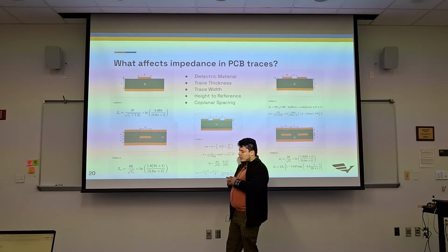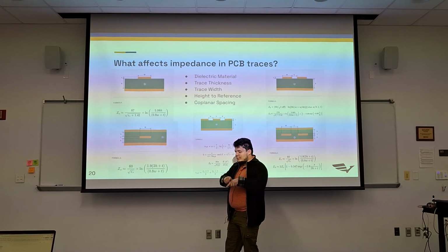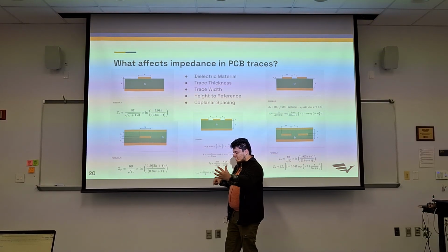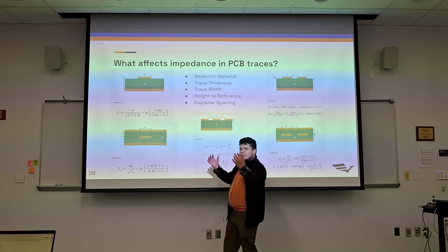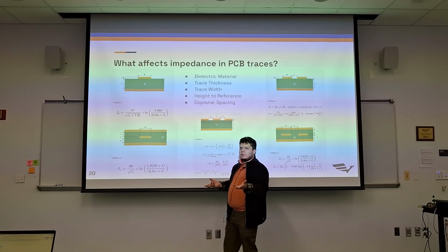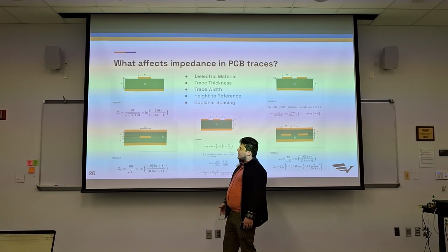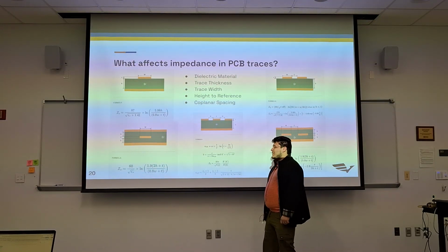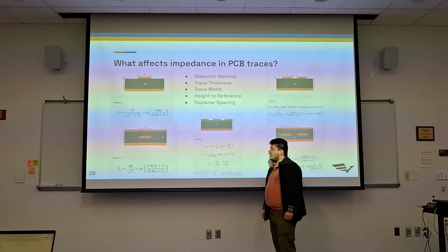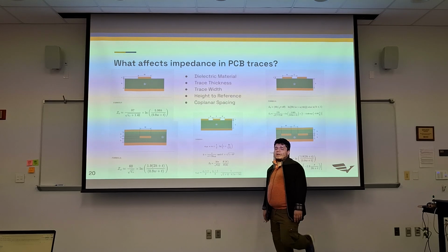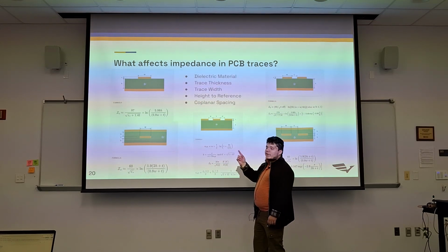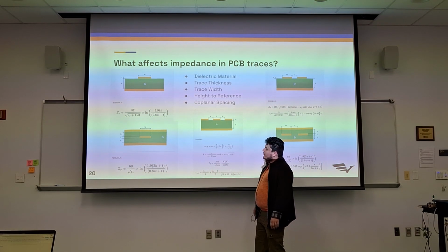This is good for when you need a very specific RF signal to travel from one board to another, and you need that shielding on top and the bottom because it's in a noisy environment and you don't have a coax cable. That's basically the time you would use something like this. It's cool to know, and I'm happy to talk about some designs that use that. I don't think you'd use it in Formula because you're not really dealing with many megahertz or anything that is sensitive to it, but maybe it'd be a cool challenge to really optimize for that signal integrity. So it is a way of doing that.